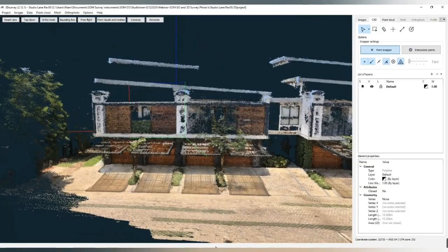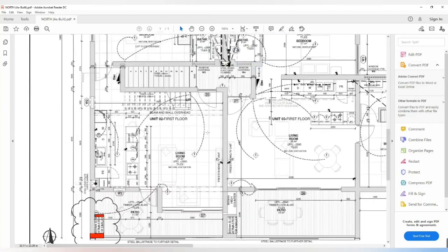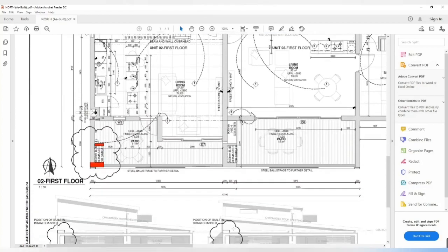When we look at the original design, we can see that the physical length is 13.340 meters, and we can see that it's taken from the outskirts of the corners of the building. So that means that our line has a deviance of about 12 mil according to this sketch. Just to zoom in and make sure that the dimensions are correct. So that's 13.340, and let's go back and see what the exact comparison was in 3D survey.